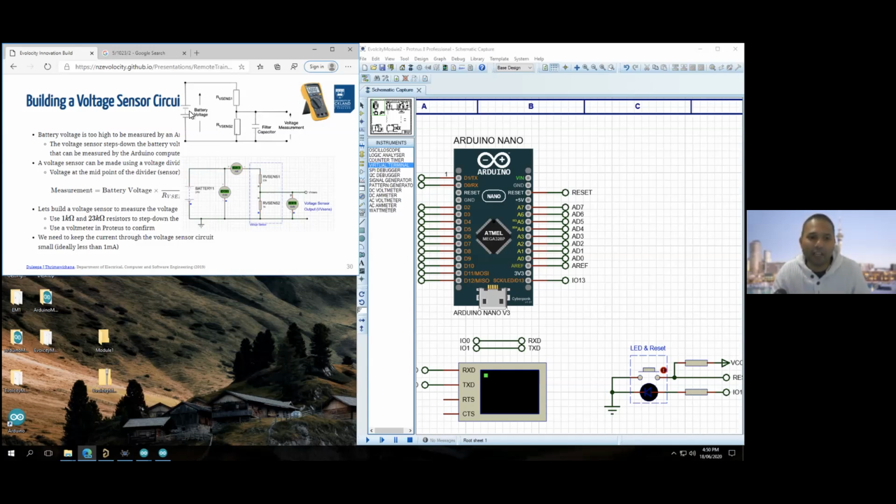And what you have to do is figure out the maximum battery voltage you're going to get. So when the battery is fully charged, it might be 28 volts. Right? Then you decide this resistor and this resistor so it brings it down to below 5 volts from that maximum battery voltage, 28 down to, let's say, 4.5 volts. So do you get specifically designed resistors for different amounts?